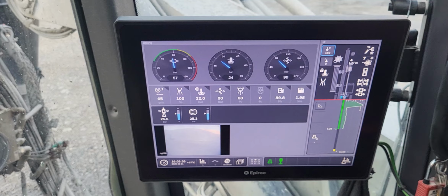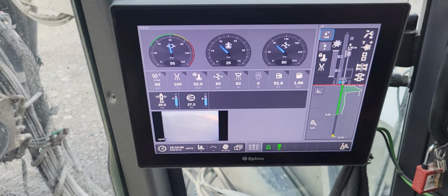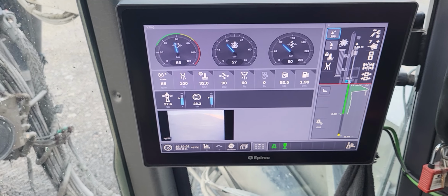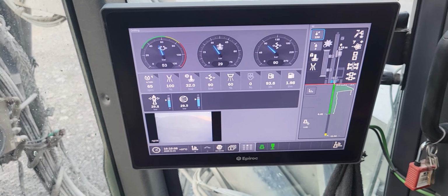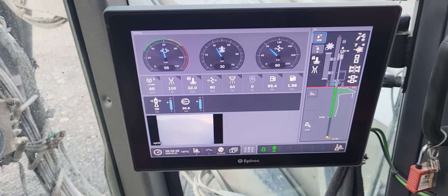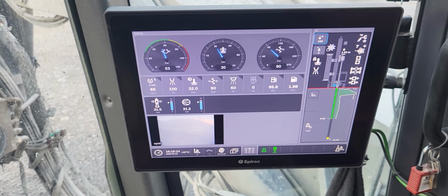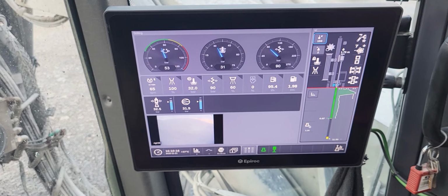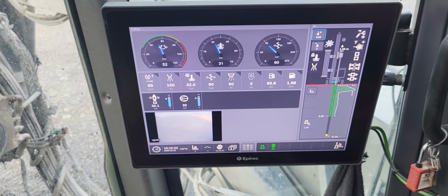We have the 32 bar of air pressure. Now the operator is using around 60% of water, because the rock is soft, so you need to stabilize the soil, and as well, since they don't have the dust collector, it's not possible to go too low in the water without having dust.